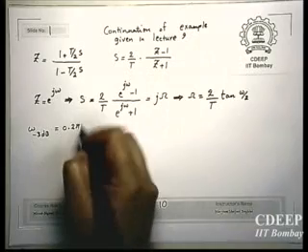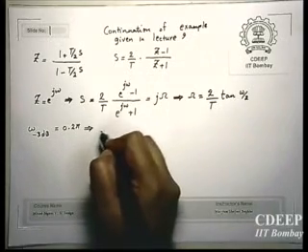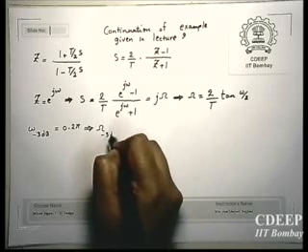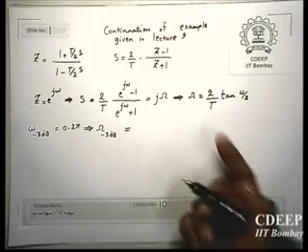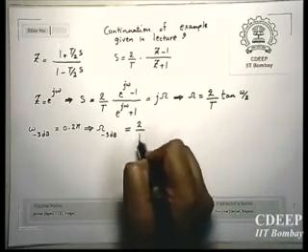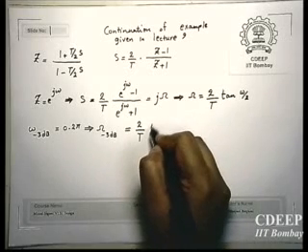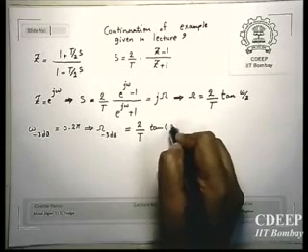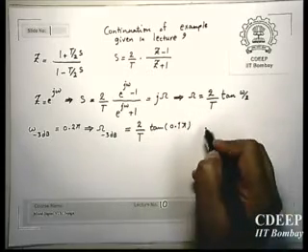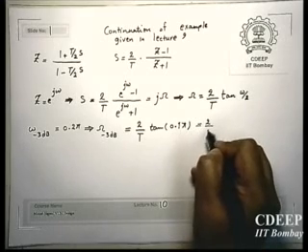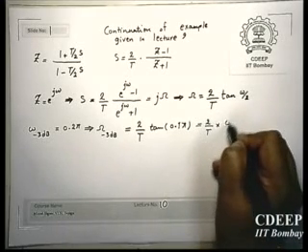So from here, capital omega minus 3 dB will be, now we have this value, 2 by T multiplied by tan 0.1 pi, which is omega by 2, which now will be 2 by T multiplied by 0.325.